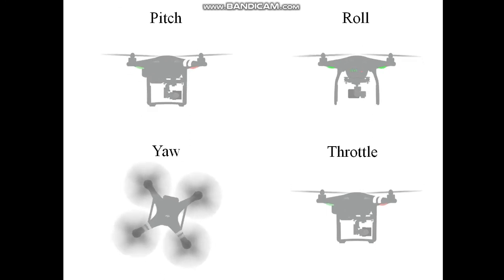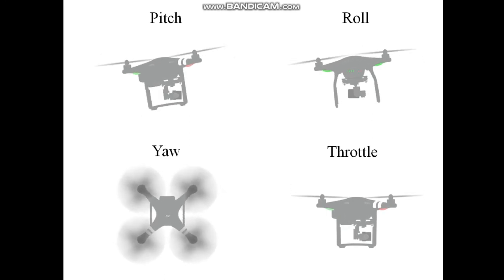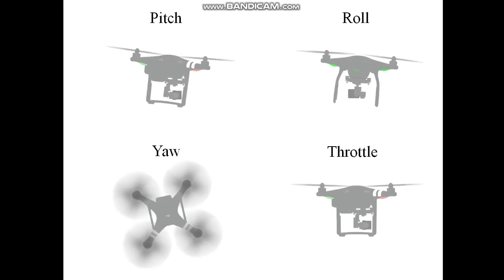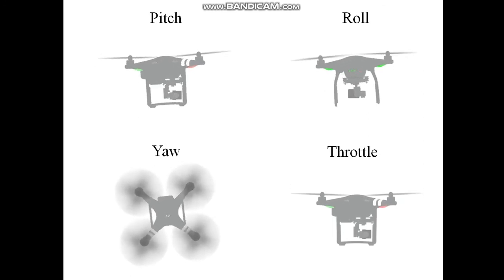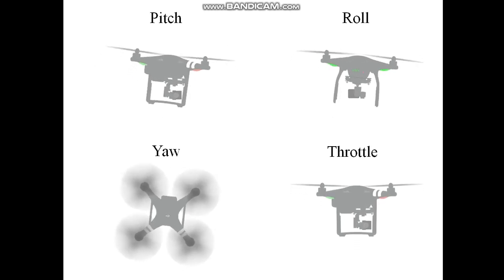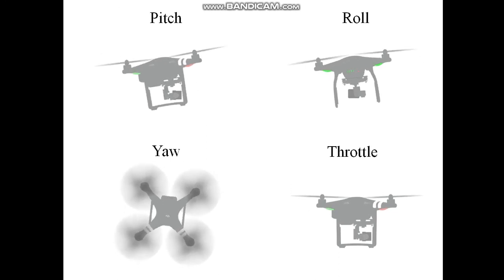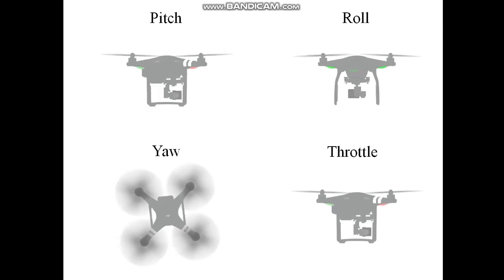Now it's intriguing how the drone flies in different directions and at different speeds. What's the design mechanism behind it? So basically, in order to pitch or roll the drone, one propeller would speed up while its opposite partner in rotation direction would slow down. The result would be a roll or pitch moment caused by the difference in thrust produced between the two propellers.